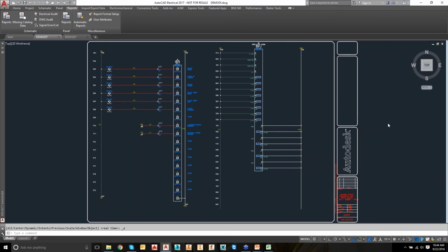Okay, what about, can I add my own catalog information for maybe part numbers, and can those show up on a drawing? So the catalog information is, and actually we had another question from Timothy. He wanted to know if it was something we create or something we grab from the internet. So it's not something you grab from the internet. Basically, the catalog is a database that comes pre-installed with AutoCAD Electrical, but you do have the ability to add your own information to it. It's simply a Microsoft Access database, or it can be a SQL database now with 2017, depending on which you choose.